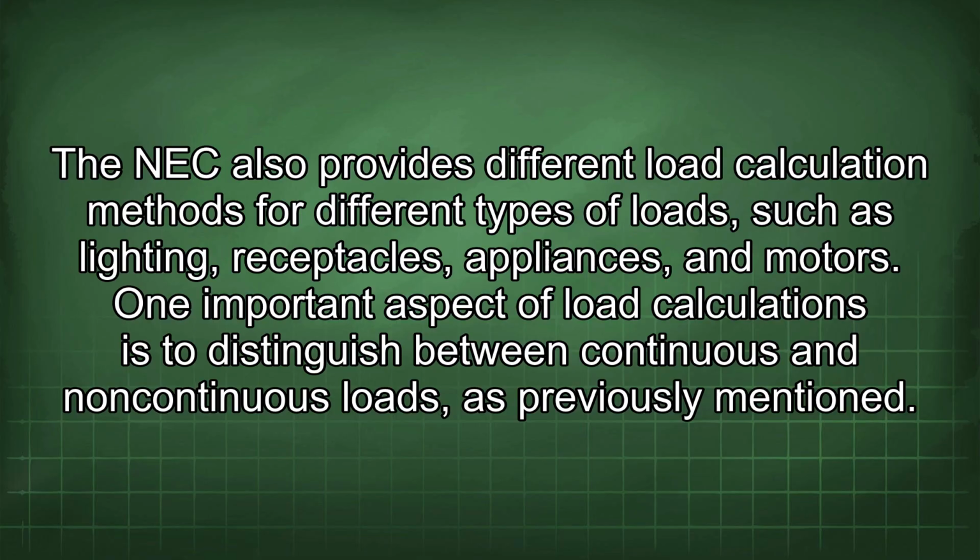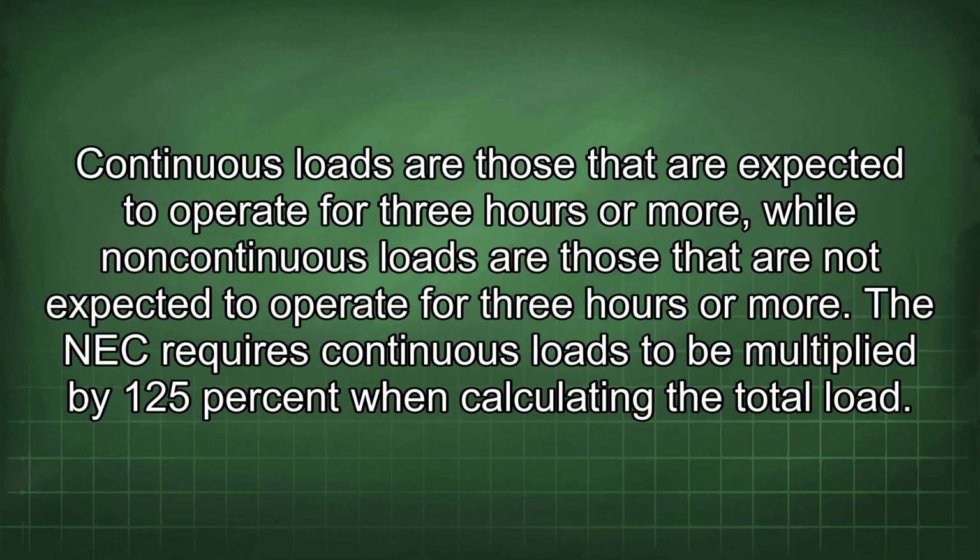One important aspect of load calculations is to distinguish between continuous and non-continuous loads, as previously mentioned. Continuous loads are those that are expected to operate for 3 hours or more, while non-continuous loads are those that are not expected to operate for 3 hours or more.